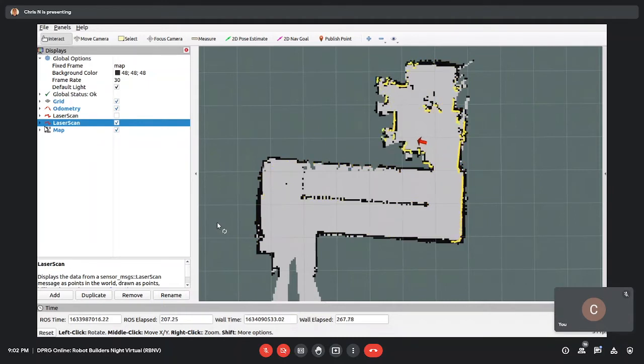It turns out for some of these algorithms, the update rate of the LiDAR is not what really matters the most. I can crank it up to 20 hertz, I do 15 right now. A 5 hertz update rate is perfectly fine, but it's the exposure time that matters. If it takes too long for one scan to complete, that's when you get completely distorted data. So I'm going to run the LiDAR as high as I can afford to before it vibrates, but that doesn't mean I need to process the LiDAR data at 15 hertz.